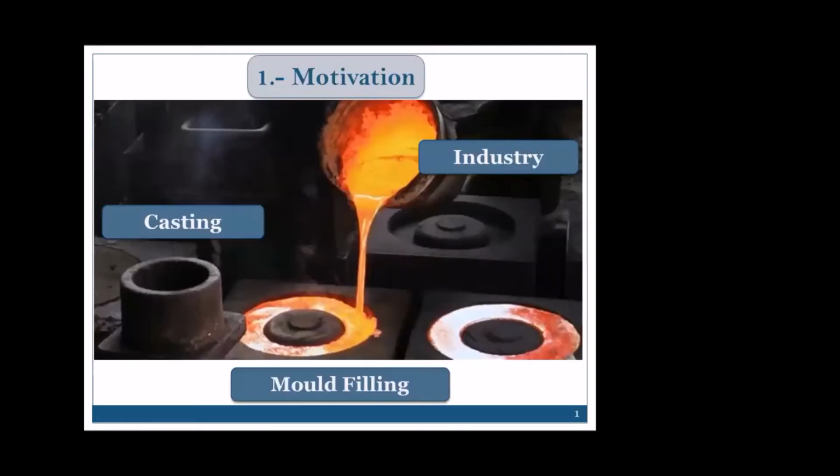So the motivation of this modeling is the developing of a modeling computational tool for the casting processes, since they are one of the most widely used techniques to mass produce metal products for different applications. These processes begin with a step corresponding to a mold filling, in which molten metal is poured into a water-cooled mold, where heat from the nearby metal to the mold walls is extracted, causing its solidifications.